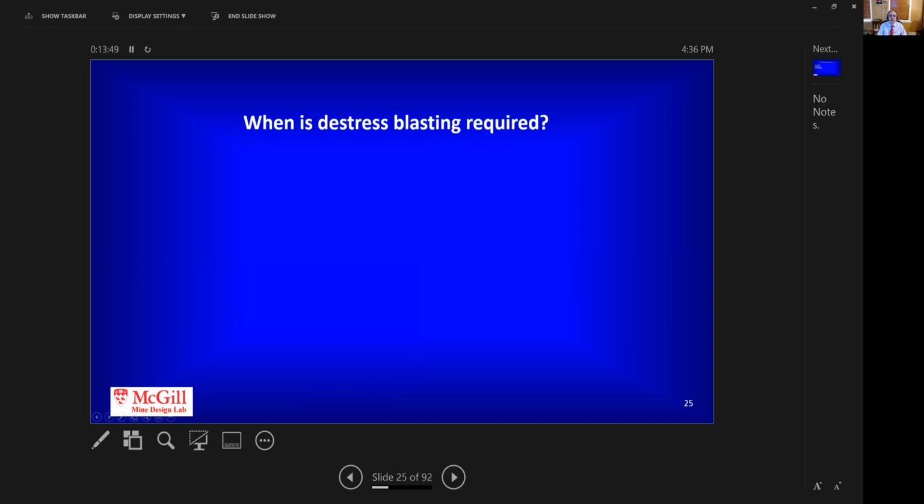So the question is, when is distress blasting required? Do we have to do it arbitrarily, routinely, never, or when? Well, if you're in a brownfield, you have many evidence of the need for distress blasting. Seismic activities is a major indicator. Rock burst damage, spalling, ejection, strain burst activities. All these are evidence that you do need to consider distress blasting or preconditioning.